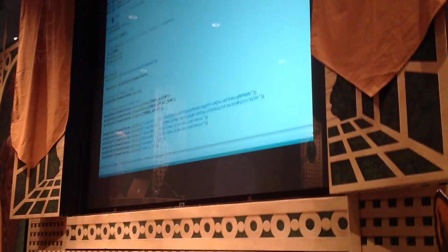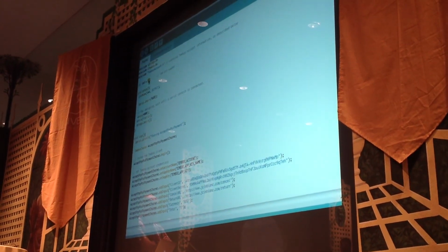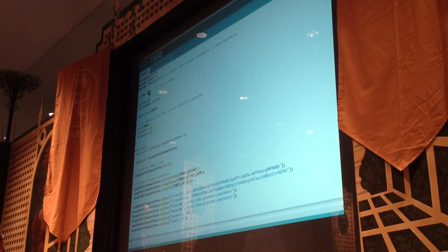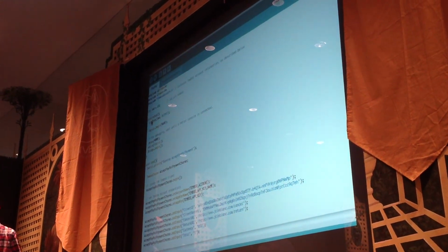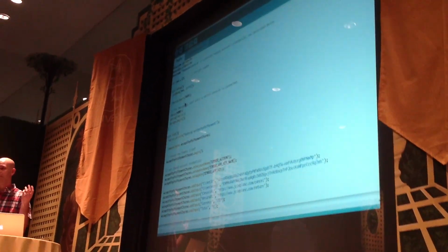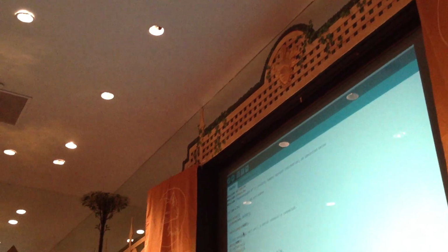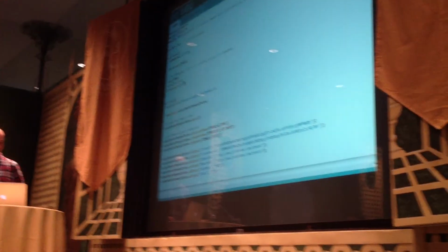So what the code is actually doing in the LED, we're setting the digital pin that we're going to use to control the LED to pin 13. This can be any of the pins in that line from 1 to 13. Then in the setup, we are setting the pin mode that we should be communicating with for the board. We're going to begin the serial monitor. The serial monitor is going to actually be how we debug. Think of it like the developer tools on Chrome. It's pretty much the same. It can output data. And then we're just going to start the bridge and set up some debugging information.